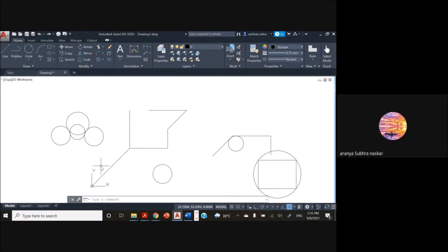Is that clear? If the radius were not possible in some case, what happens? Then you will see. Okay, let's try that. So I'll take this and give a very small radius, say 2.5. It is not feasible that it will touch both the circles, right? Just 2.5, and you see that the circle does not exist. So this error message will be displayed.